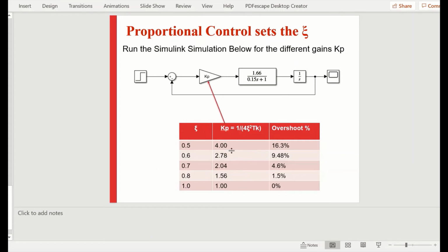You've got a little table which you've developed for your Kp, simply by putting these equations into here. These are the gains we're going to try, and we're going to get 5 different results out, so you need to make a note of which is which. You can tell because in the bottom left hand corner of the simulation or the real-time results, it'll tell you what Kp is.